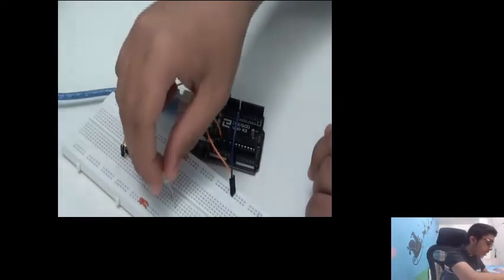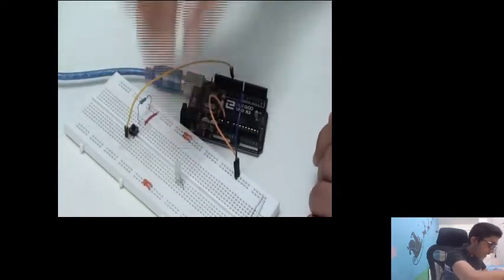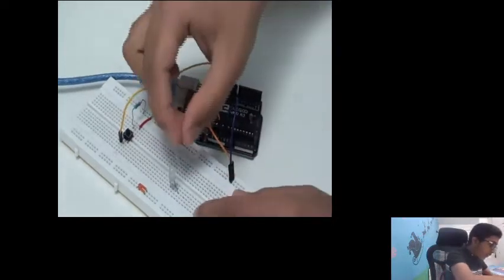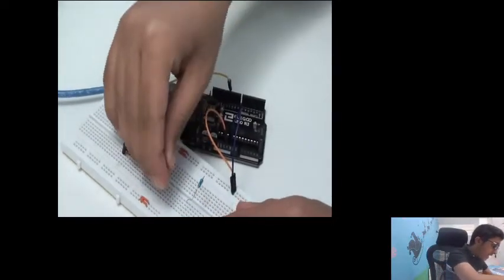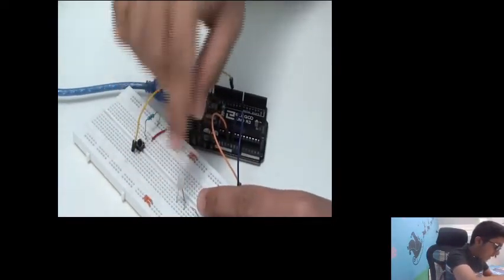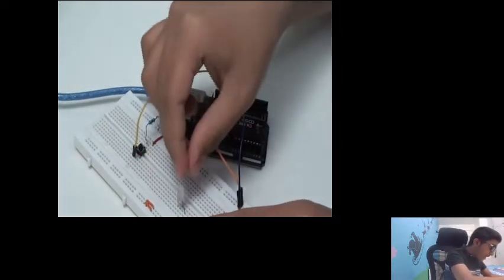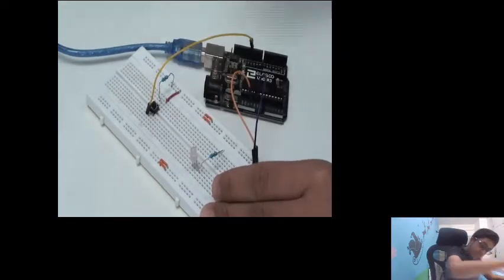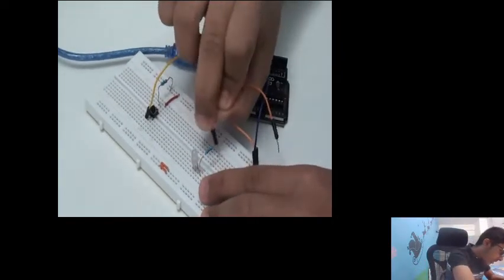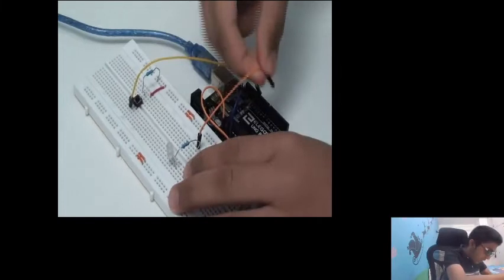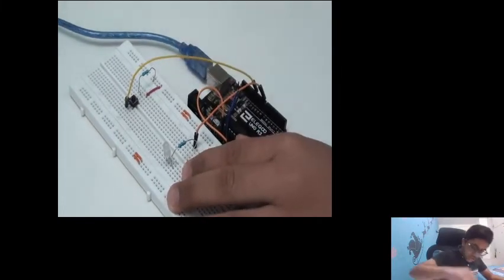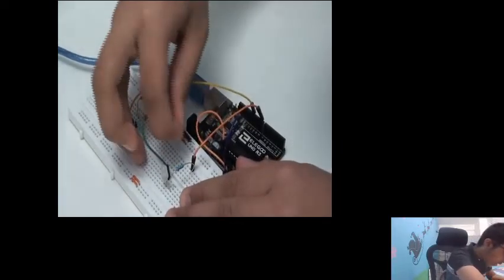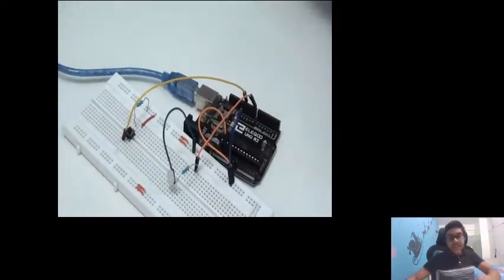Now let's move on into making the LED circuit. The LED circuit is always same as before. We're going to hook up the LED and put the positive terminal on this side, on my left, and we're going to take a 220 ohm resistor, right? And through that 220 ohm resistor, we are going to connect it to any one digital pin. I am going to connect it to pin 8, and the other lead, the negative one, goes to ground. Alright guys, that completes our circuit.